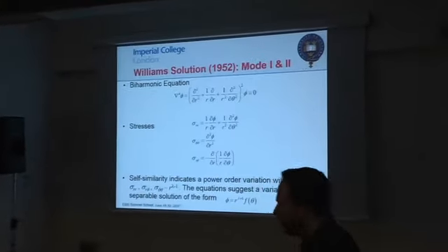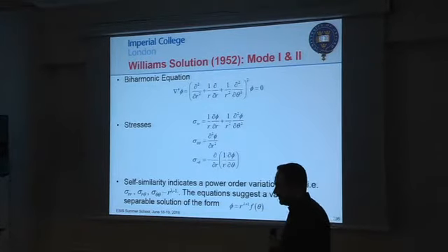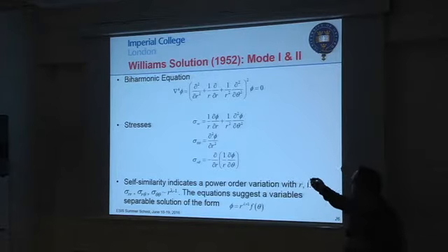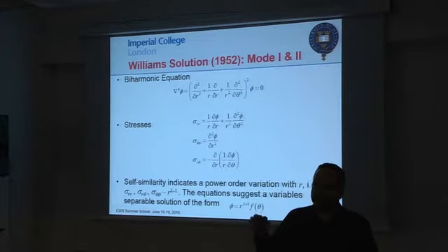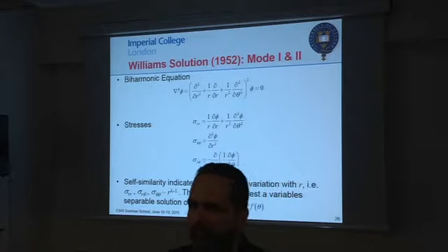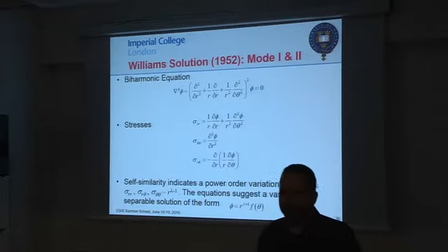So again, if you have never come across this, all there is to understand is that for the system to obey equilibrium and compatibility in some form, you need to satisfy this equation, and the equation can be satisfied for a certain function phi. That function is what you want to find to get your solution to your problem. And if you define phi, you can define all the stress field, because the components are a function of the derivatives of phi.